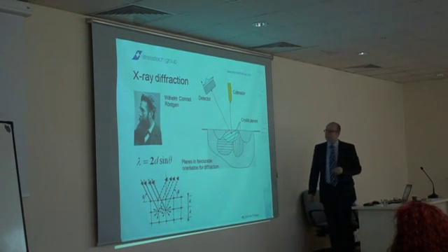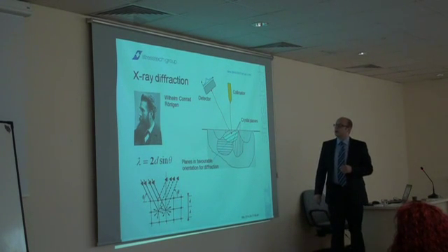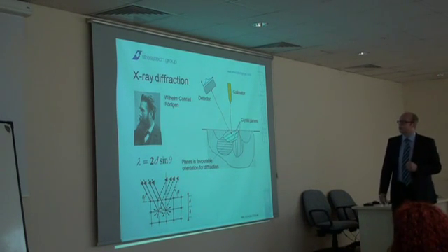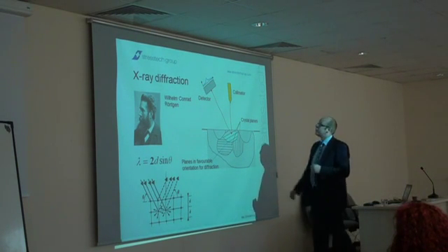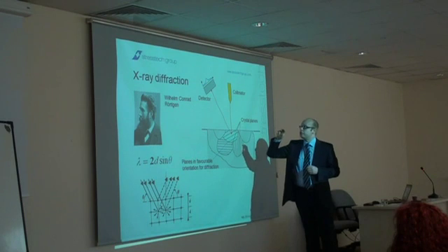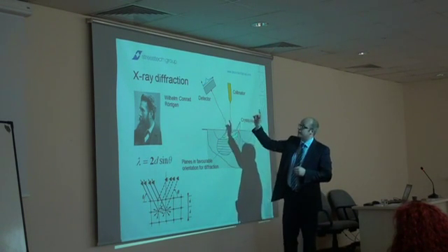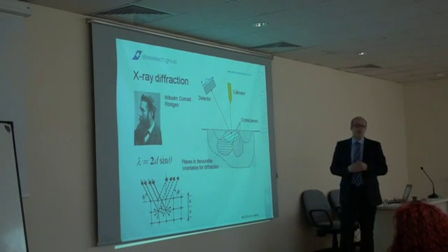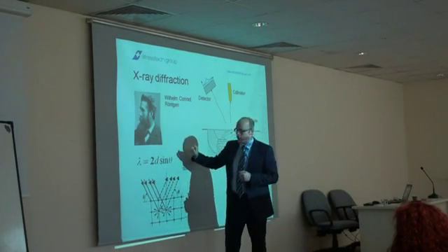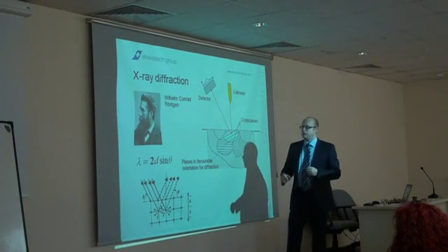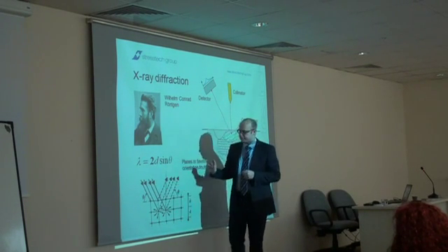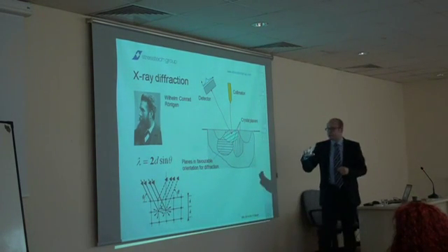So let's go to X-ray diffraction, because this is another application. Here I would like to say a couple of words about the technique, or the theory, behind X-ray diffraction. What we basically have in an X-ray diffraction meter is an X-ray tube, a collimator and detectors. And this X-ray diffraction method is based on this law. Of course we know the wavelength, and we know the diffraction angle. But what we don't know are the d values between the atom planes.